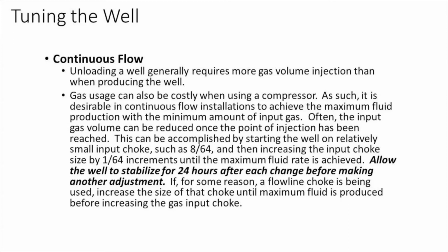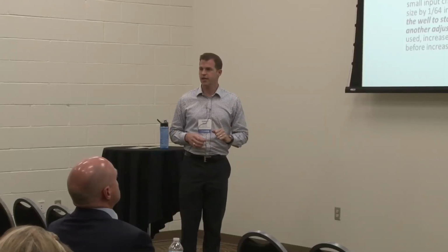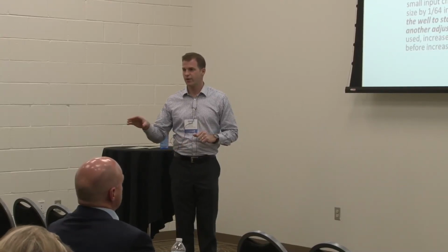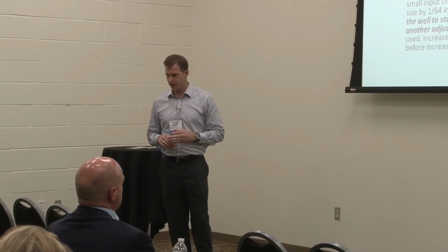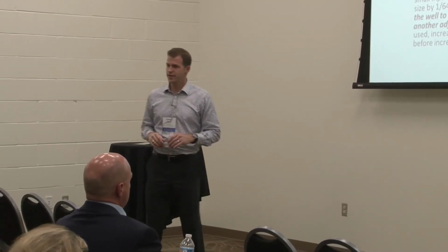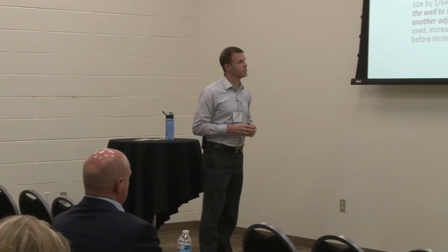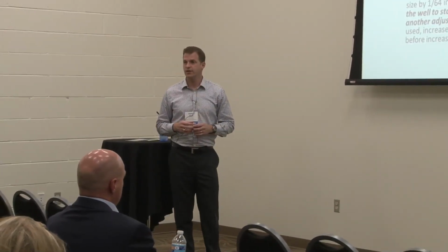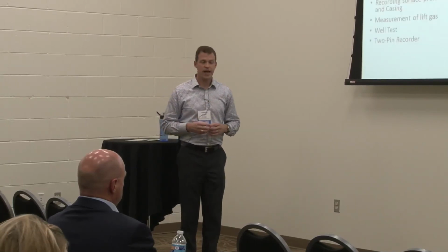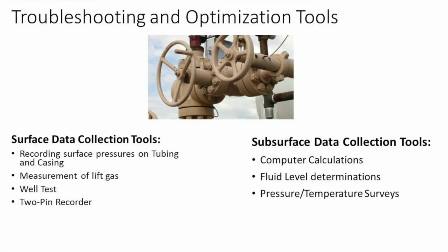With horizontal wells, the rate of decline is relatively quick, usually 90 to 120 days. You can cut production in half based off of the deliverability of that well. So if an operator or a pumper set the injection rate for a high fluid rate, and 3 or 4 months down the road it's half that production rate, the injection rate needs to be adjusted. That can be identified through optimization and changed in an incremental fashion until you get your optimized injection volumes. Some of those things can come through your tubing velocity curves and through nodal analysis as well.